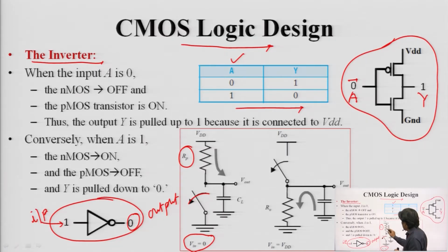With the help of this small resistance, from VDD the current will flow through this resistor and it will charge the capacitive load, clear, as long as we have a supply and we have 0 as an input, okay, the logic 0. That means the capacitor will slowly charge and will charge fully over time, right.